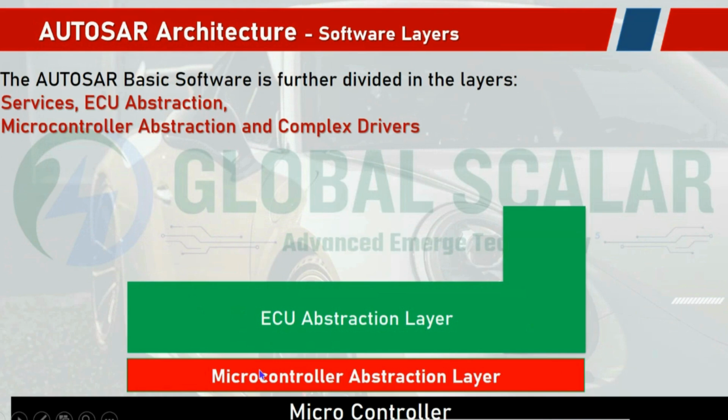Next we have the ECU abstraction layer, which we call ECU AL. It abstracts the ECU specific hardware details and provides services to the upper layers such as memory management, flashing handling, and hardware diagnostics.